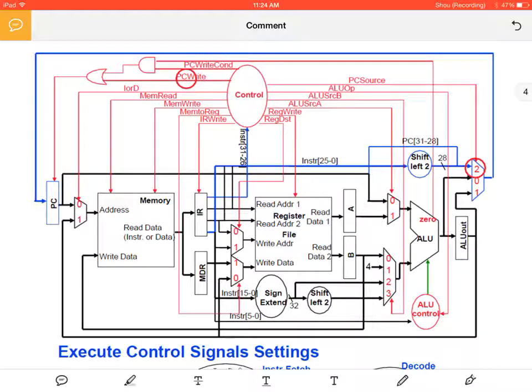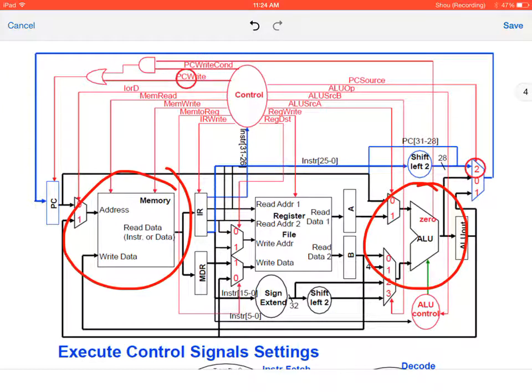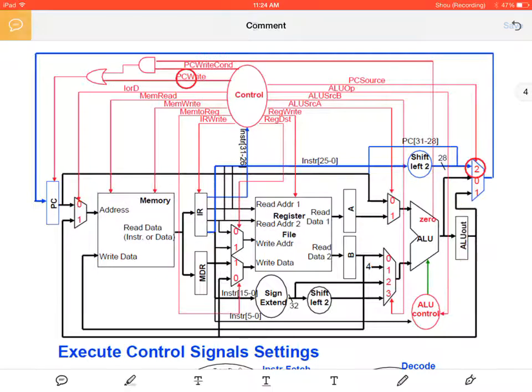Okay. And so as part of the compromise, we take the 2 adders. We're using the finite state machine to calculate those in the first 2 stages instead of having to add 2 adders to our data path. And we've combined instruction memory and data memory into one memory. And we've used this instruction register to prevent that structural hazard by allowing us to say whether it's an instruction or we're getting memory from the data memory. And what's MDR? MDR is memory data register.